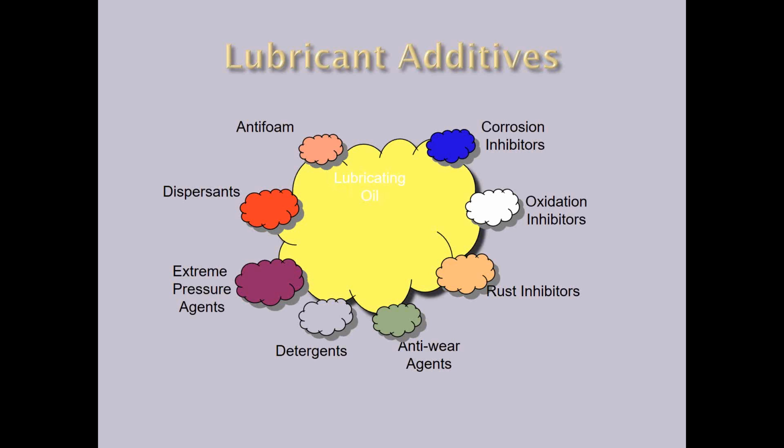There's dispersants in your engine oils. There's extreme pressure additives, all your EP oils and greases. These are additives that are in there to lay down an extra surface on our component under high load, high temperature conditions and keep the component from wearing. Detergents in your engine oils. Anti-wear, all your hydraulic AW oils. These are anti-wear additives. Very similar to EP additives. They lay down an extra coating of protection. They can be phosphorus, they can be zinc in hydraulic oils.